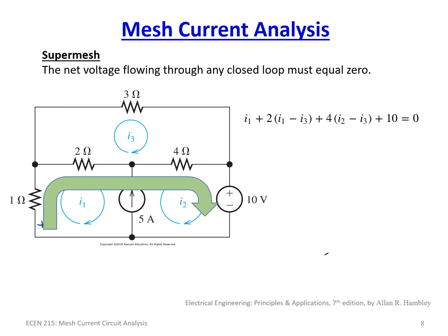Then we have this 4 ohm resistor here. Its net current is I2 minus I3, because I2 is going like this. However, I3 is flowing through it like this, so you get the net current flowing through it, which is I2 minus I3. And then, since we're following this arrow, we're entering the positive terminal of the voltage supply, so we add it, and so we end up with this equation. All of that must equal 0. So this helps us reduce things.